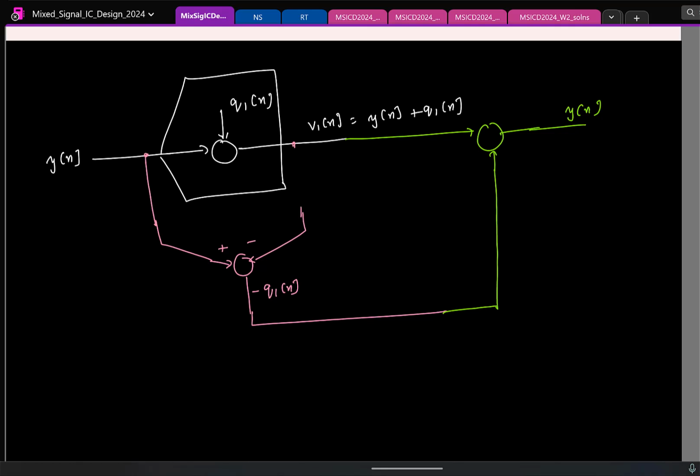A DAC. And one nice thing here is, remember that this DAC here is not trying to take the digital data and give a continuous time signal. Remember, this is all still samples. It is just taking digital code, let us say 1, 2, 3, etc., converting it to voltages like this. This can be done without any error.